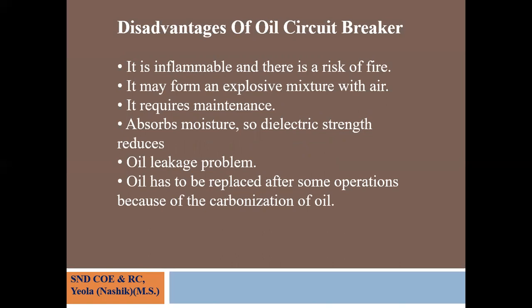It requires maintenance. It absorbs moisture, so the dielectric strength of the oil reduces. The fourth problem is oil leakage in the oil circuit breaker. The fifth problem is that the oil has to be replaced after some operations because of the carbonization of the oil.